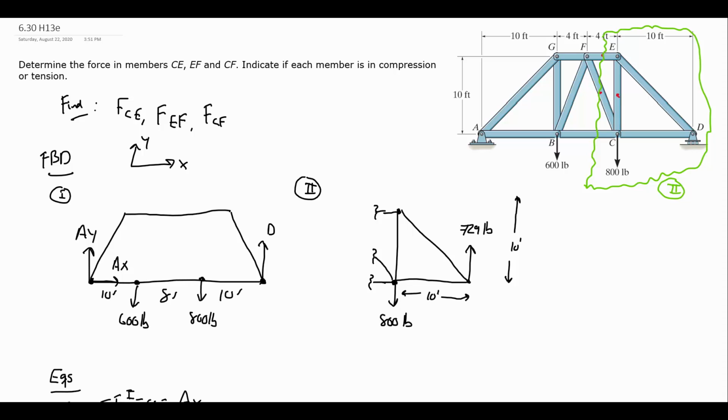So that's where my cuts are, these squiggle lines, and I'm going to be assuming tension is the force that was in those beams. So now I can see FEF coming out of here. I cut through BC, I can now see FBC. And coming out from here, I can now see FCF.